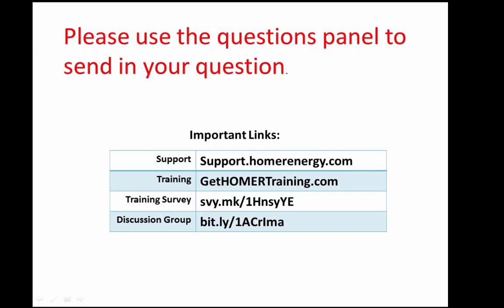Thanks. Can the system prevent stupid results? I'm just reading the question, i.e. running a genset at only 20% load? So that one, yes, we prevent that. We do an hour-by-hour dispatch, and one of the factors that you specify for a genset is the minimum load.